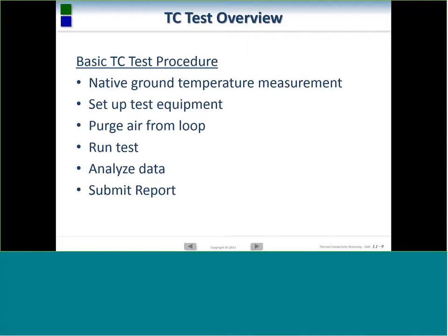After the test equipment has been hooked up and you have purged all the air from the loop, air purging, very important. Any kind of air that would be left in a loop could conceivably get into the pump, cause it to airlock, cause the fluid to freeze up, and then you end up with a flash boil of the water when you mix the heating elements. So being careful to purge the air, very important, because it can also cause a lot of low flow conditions, which will vary the heating state and flow state in the test throughout the 40 plus hours that you're running it.